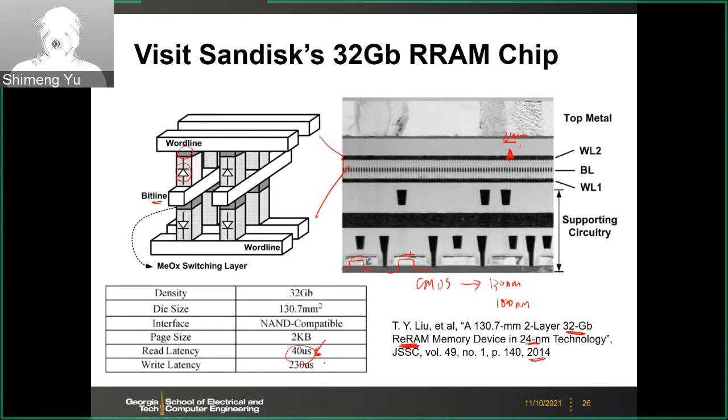So in other words, in this particular design, the array in terms of area is pretty small, and the peripheral circuits, because each transistor is much larger, we cannot have too much resources or areas for the peripheral circuits because each individual transistor takes so much space compared to the memory array. Therefore, they have to share those sense amplifiers across multiple blocks.